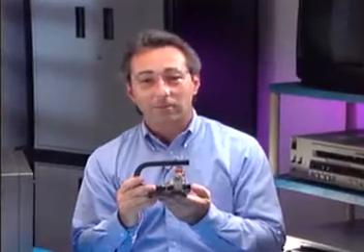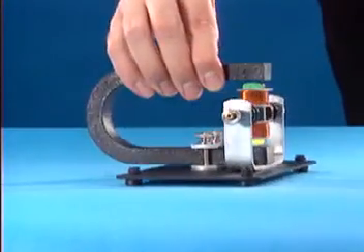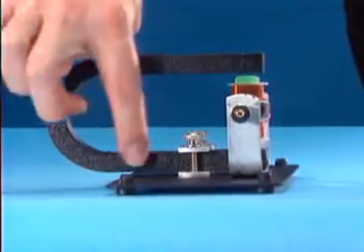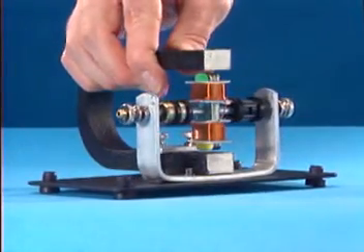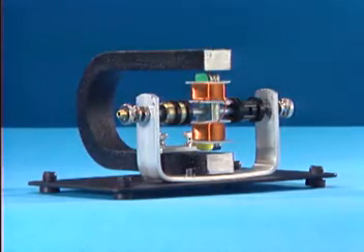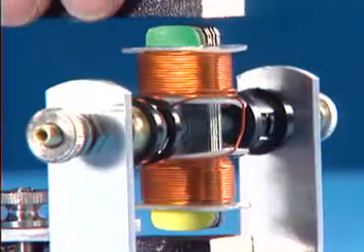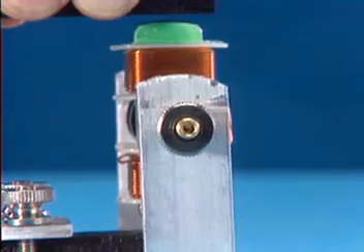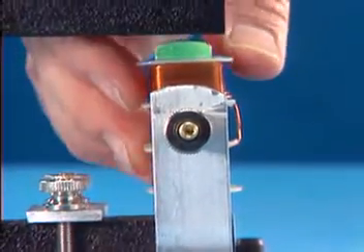In order to better understand how AC current is produced, let's look at a highly simplified version of an electric generator. It's made up of a coil that revolves between the poles of a horseshoe magnet. Notice that the coil has been colored green at one end and yellow at the other to keep track of their position during rotation. Let's slow one revolution of the coil way down to see how it interacts with the magnetic field through which it's traveling. Although it'll be stopped in certain positions, you must remember that in order to generate AC, the coil is constantly spinning. As the coil revolves through the magnetic field created by the 2 magnetic poles, it cuts through the flux lines at different angles.